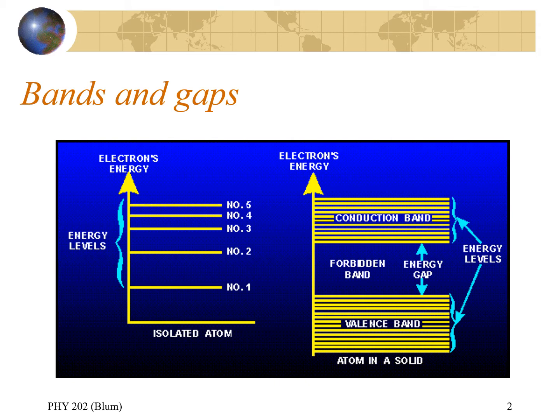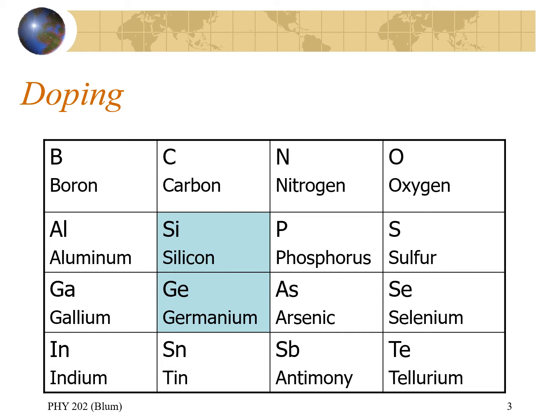And then we filled up those bands with electrons in the lowest energy levels, and the last filled energy level, the Fermi level, its position within a band determined whether the substance was a semiconductor or a metal or an insulator. Next, we want to consider the effect of doping, sort of sprinkling in some atoms that are nearby the semiconductor in the periodic table.